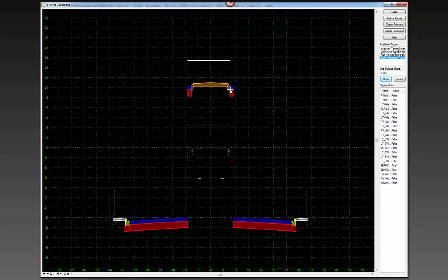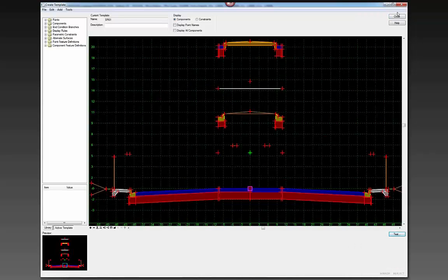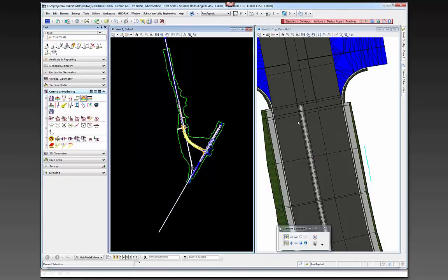And what happens is this pavement will try to follow wherever that traffic separator line is at the slope of this pavement here. And the reason for that is, in case it was a super elevation, it would follow that same slope. But what ends up happening is the elevation of the lane obviously goes up above where a normal crown would be. And what you'll get in your model is a situation like this.